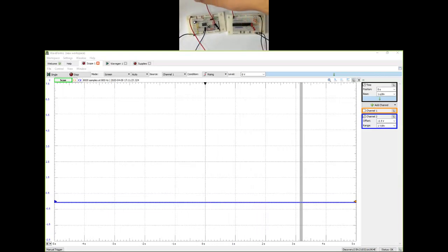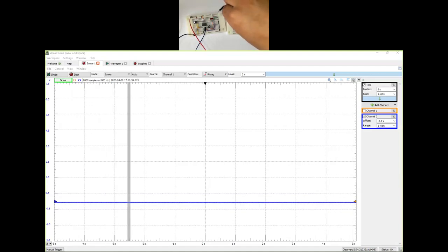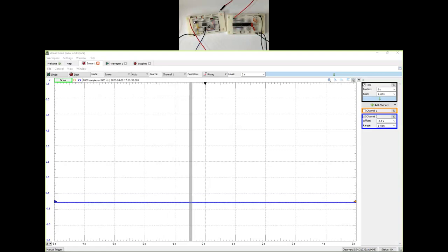So the goal is, if I took the output of the 555 timer, which is supposedly a clean pulse, and I use that to trigger a counter, my counter should count up by 1 only when I press a button, and it should not count up multiple counts when I press only one time. So that's the real test of my switch debouncer.